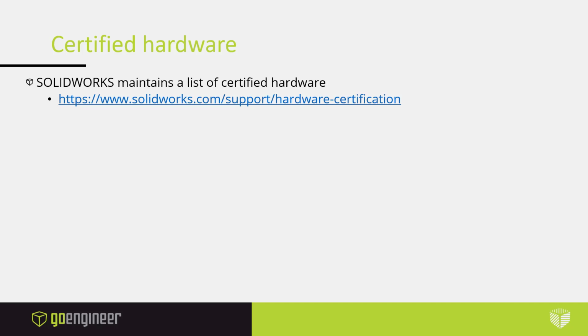Certified hardware, like I mentioned, there is a list of computers, and they also go into the GPUs, the certified video card drivers that you should be running for the version of SolidWorks. That's the website there. It's fairly intuitive to use. There's really only a couple drivers that might be listed for different versions of SolidWorks, and you just want to make sure you're running one of those.